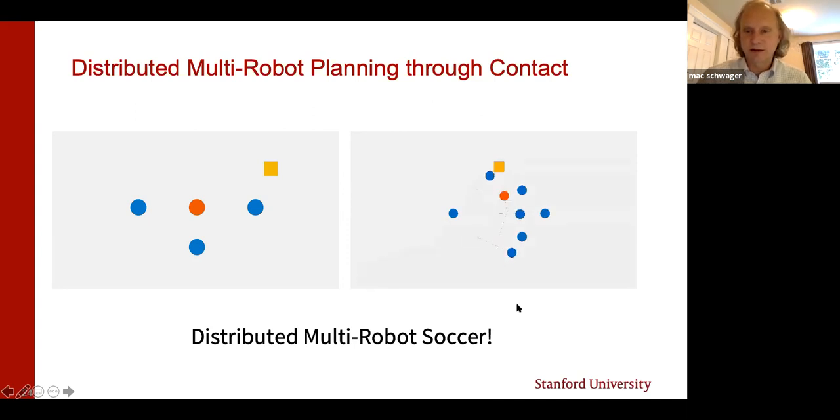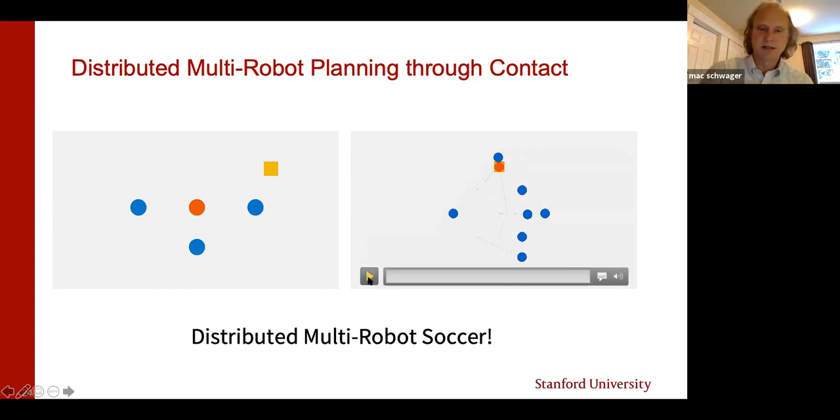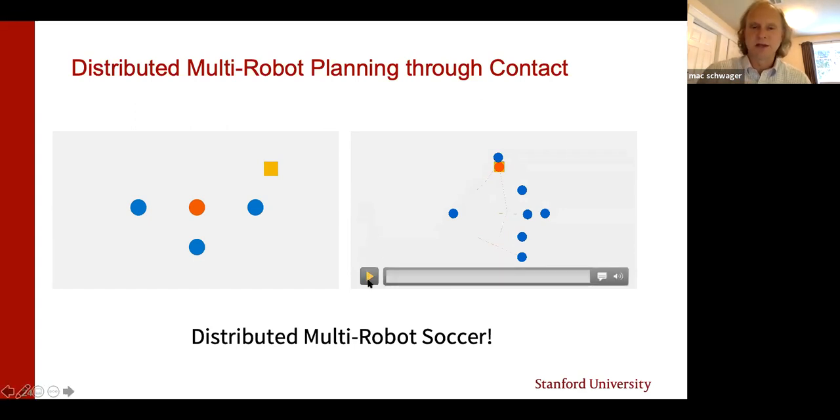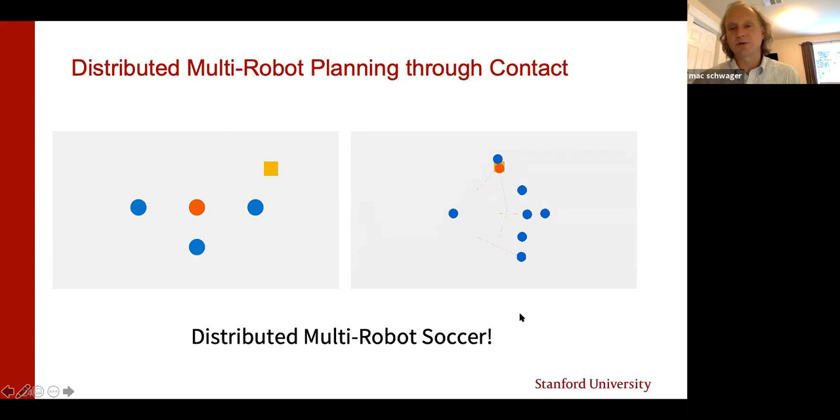And the same thing here. Same idea, but now we can actually have kind of striking maneuvers. So we can basically induce striking maneuvers based on the underlying objective problem that we're trying to solve. But you can see, by the way, we're imposing contact constraints through complementarity constraints. So if you're familiar with the problem of planning through contact, one of the common ways to do that is to impose complementarity constraints.